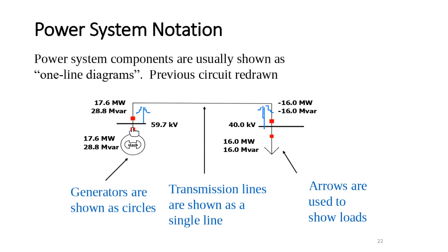If the load is giving reactive power, the load will always absorb active power. Same thing for the generator delivers. The load will always absorb, and will never give real power, will never give megawatts. But the load could give megavars. How could it? If we have capacitors here.